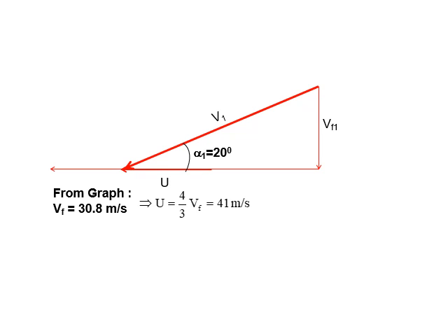Now mark the length of U, the blade velocity, on the horizontal line. Then find VR1 by joining the intersection point of V1 and Vf1. Then measure the beta 1 angle. Then draw the beta 2 angle and mark the VR2 line.